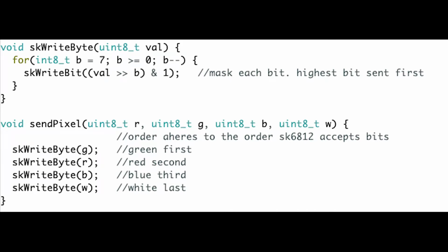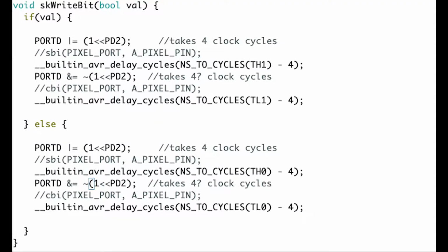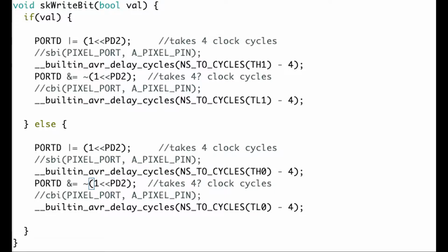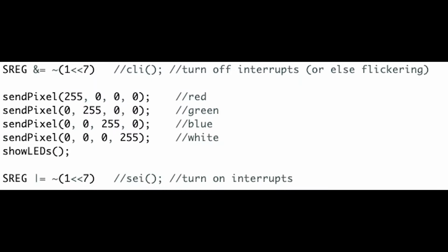Since the popular FastLED library did not support RGBW LEDs, I coded a sketch to control them by toggling pins on the AVR microcontrollers with nanosecond timing, as the one-wire protocol calls for, using the low-level port manipulation concepts I recently learned in class. This involved carefully calculating the number of clock cycles of each instruction written to adhere to the precise timings of sending bits. Every clock cycle counts, so global interrupts must be disabled when pushing the data out to avoid unwanted flickering.